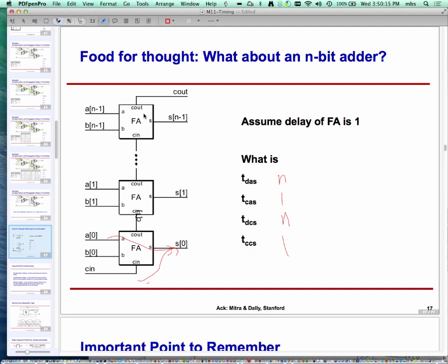Now imagine that the contamination delay of my combinational logic was too short. So when the state register changes value, the effect of that value, because of a very small contamination delay, can race through my combinational circuit and hit the state register while I'm still in that hold period, where the flip-flop would like to see a stable value. Because of a very short contamination delay, we race through this thing.